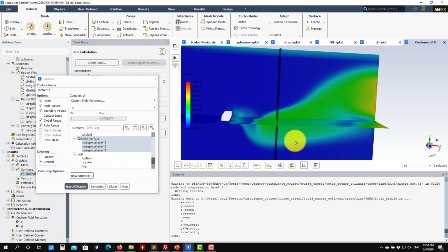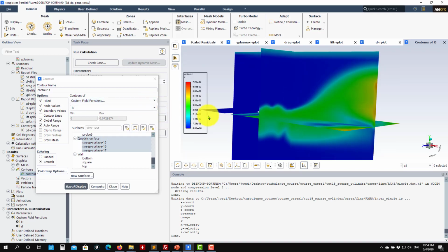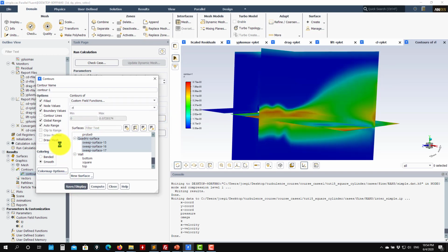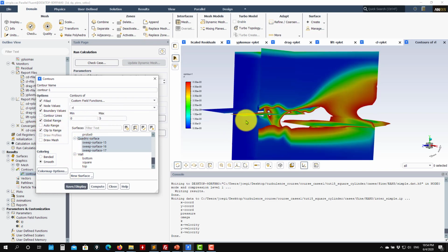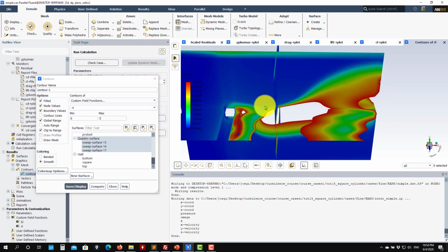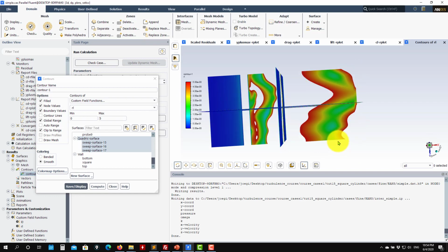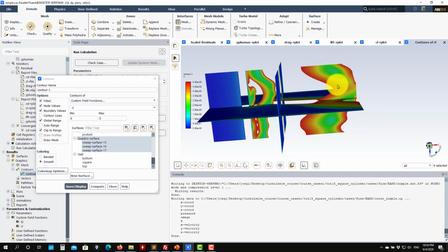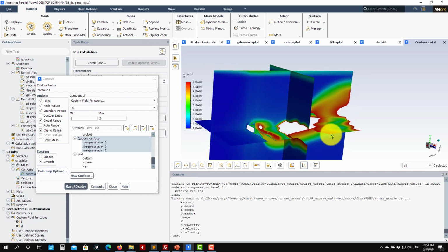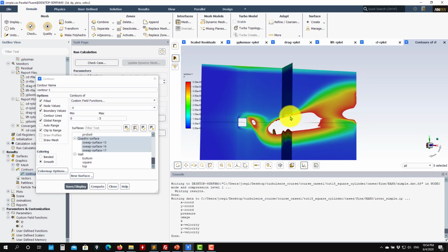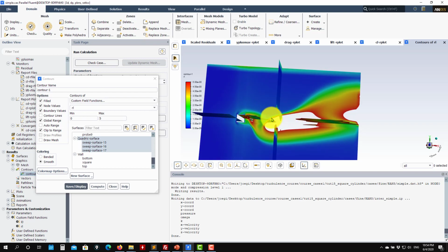So here you see the integral length scales. As you recall, in the other case, there may be some differences. In the other case, it was something much larger. And if I plot RL, I already see some difference in the maximum value, and see that now this one is much better. Okay, so see that now here it's telling you that everything is resolved. There are some areas that might not be working fine, but again, you get the idea that we went to a final mesh and now we have a better resolution.